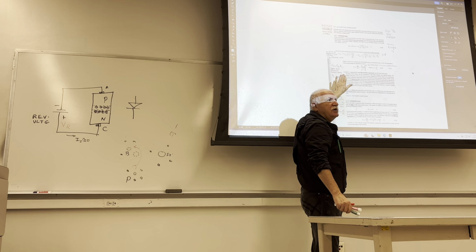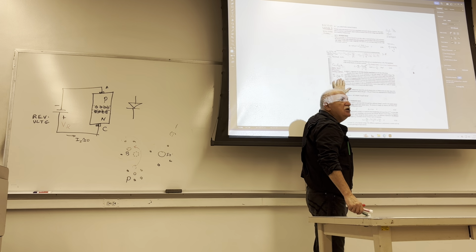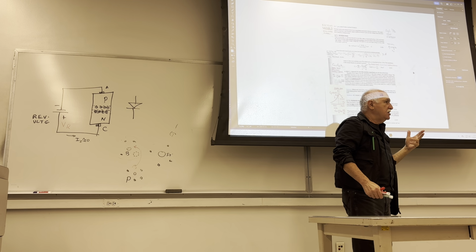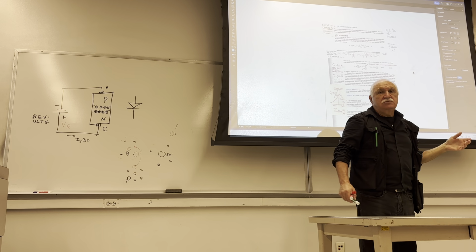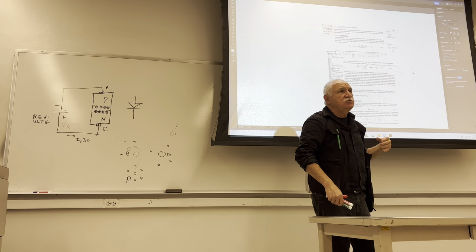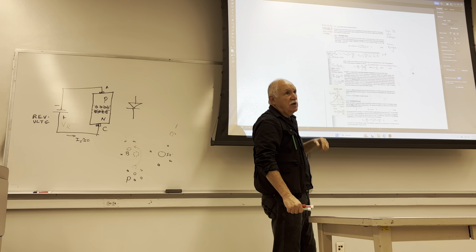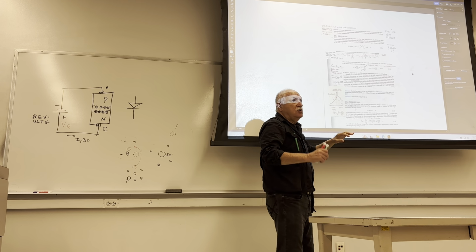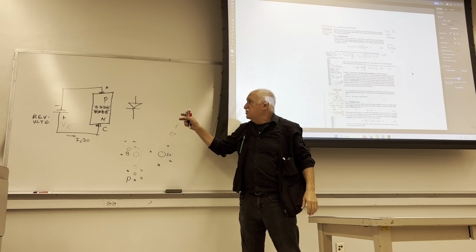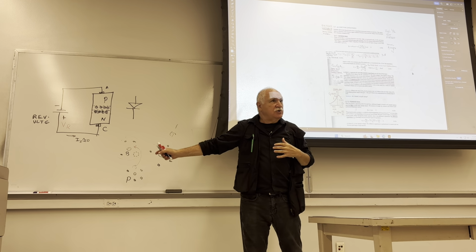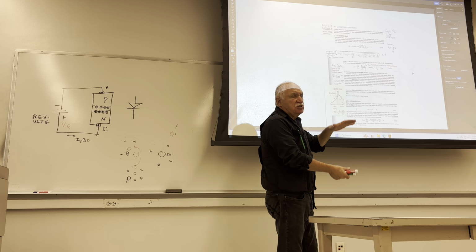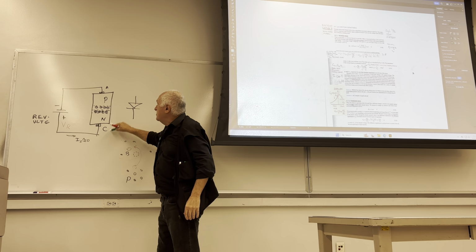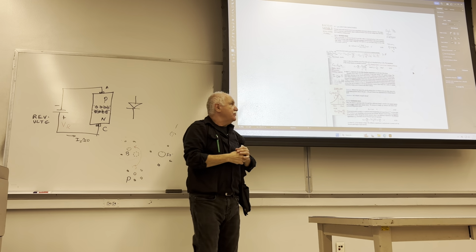These diodes are always and always meant to be used in reverse. You will never ever see that diode in a forward region of an application. You want forward current, you use other diodes. You don't use a varactor, a variable capacitance diode. The significance of that is, in the reverse region, you have no current flowing into the diode because it's reversed, and you have a variable capacitance between these two electrodes.